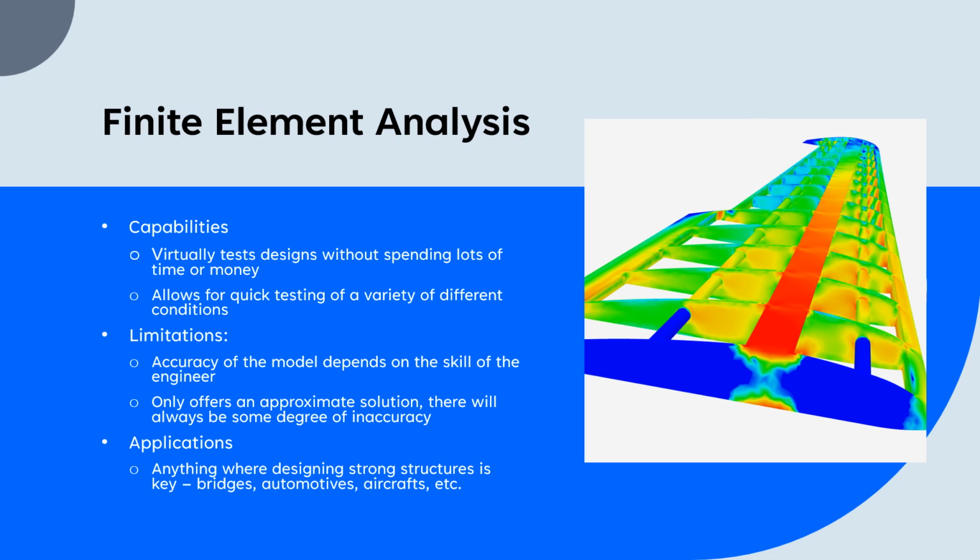However, FEA is not perfect. It is a model, and all models have some degree of inaccuracy. So the accuracy of the model depends first on the skill of the engineer, how well they know the loading conditions, how well they pay attention to the detail, like the room temperature, the attachment points, the boundary conditions, stuff like that. And like I said, it is a model, so it only offers an approximate solution. Testing it in real life may yield some results that were kind of unexpected. So it's a good starting point, but it should never be like the final point.